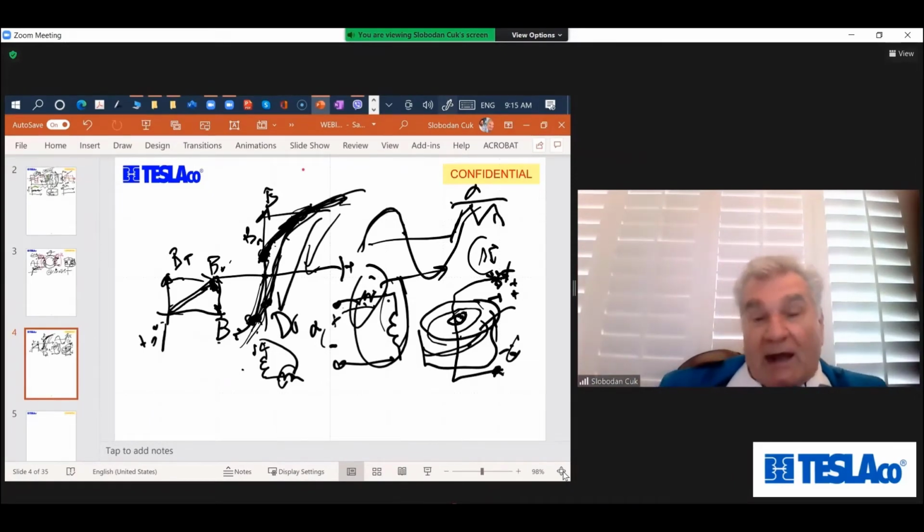So there is an active means, whether you do it full bridge, half bridge, or push-pull, to operate at the maximum flux capability without ever worrying that you're going to get into saturation of the transformer, and use the maximum flux swing.